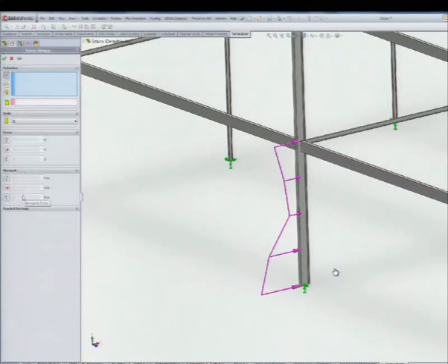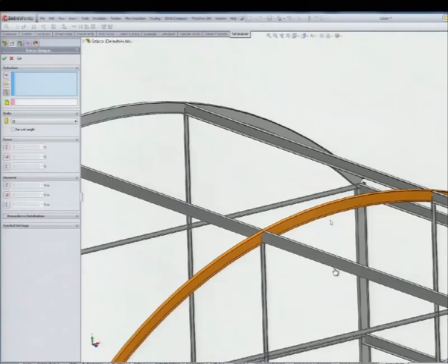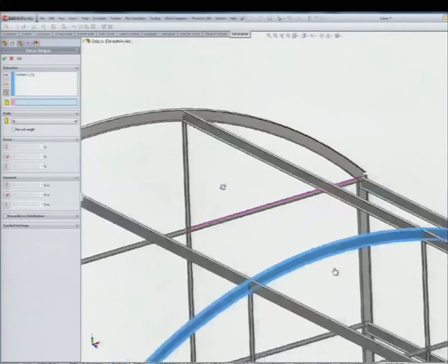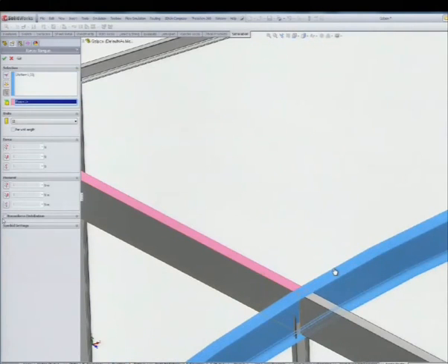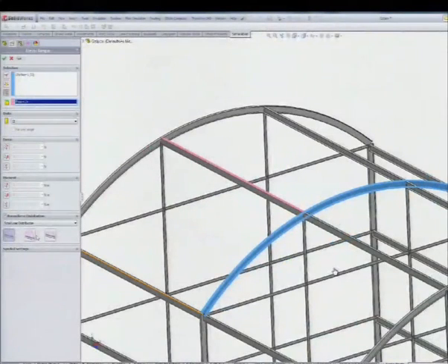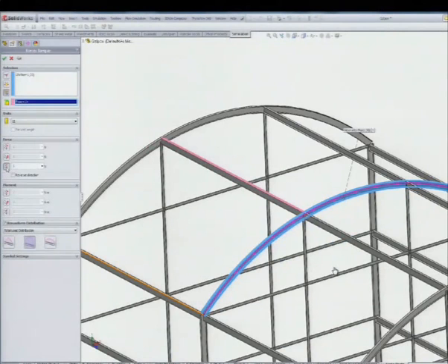And now this is a pressure acting on the building because it's the wind. And now I have to introduce the lifting force, because, you remember, the velocity of the air at the top of the building is higher than the average. And I will choose a parabolic option because it matches the pressure field.